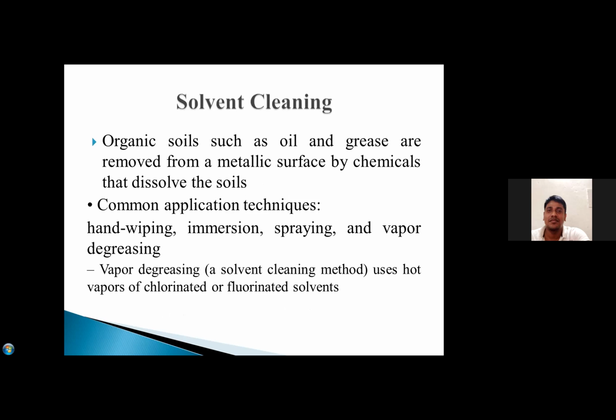Now, solvent cleaning. Organic soils such as oil and grease are removed from a metallic surface by a chemical that dissolves the soils. Common application techniques are hand wiping, immersion, spraying, and vapor degreasing. Vapor degreasing uses hot vapors of chlorinated or fluorinated solvents.